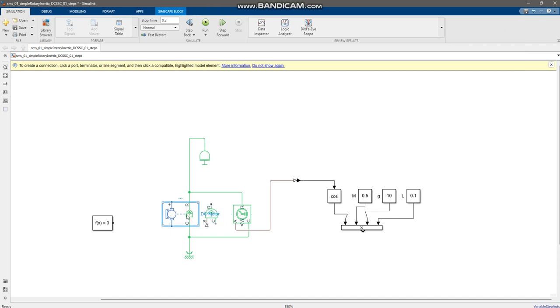So the Simscape block for the PMBDC motor has two parts, electrical and mechanical. And the mechanical side of the block will impart a torque on the inertia, and the positive direction of that torque would be from C to R.